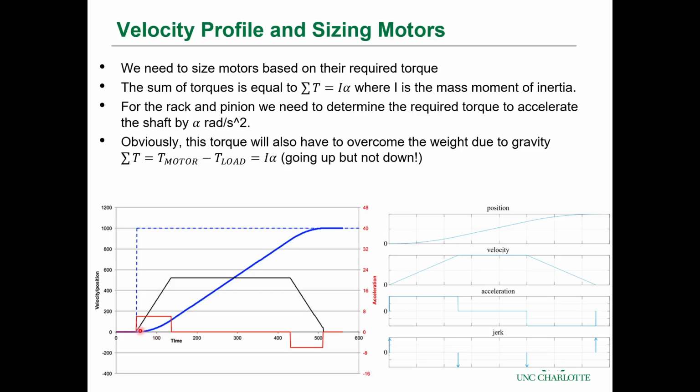So what you're going to have to do is say, how fast do I want my cart to go? How long do I want it to take to get from the bottom of the ramp, the ladder, or the structure all the way to the top of the roof? And that'll define this. And how long do I want it to take to get up to my desired velocity? Then you can pick, based on those numbers, the desired acceleration, and then from the load that you are going to experience on the shaft and the shaft's moment of inertia,